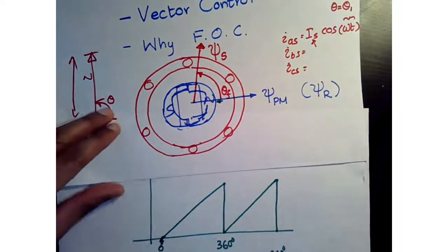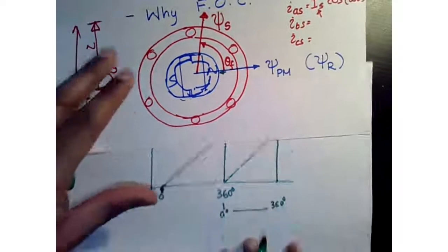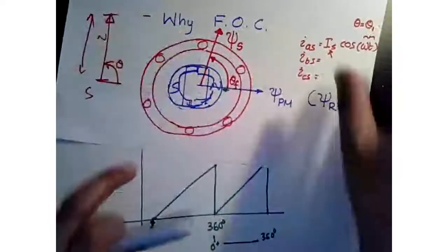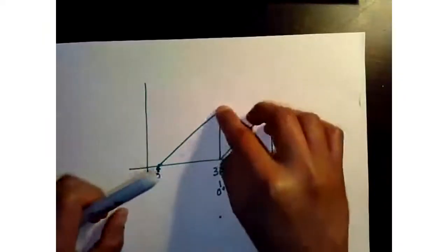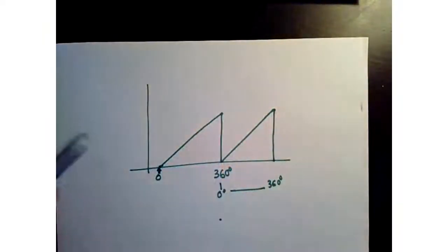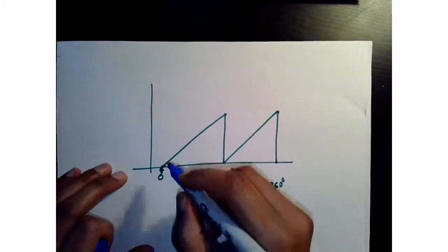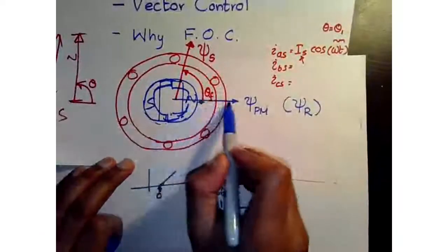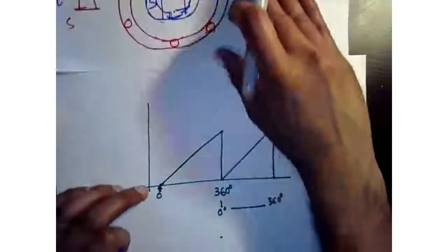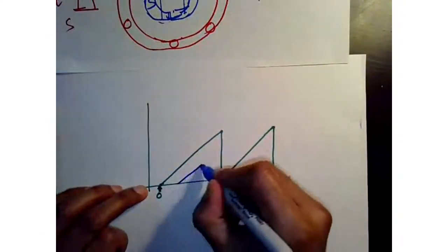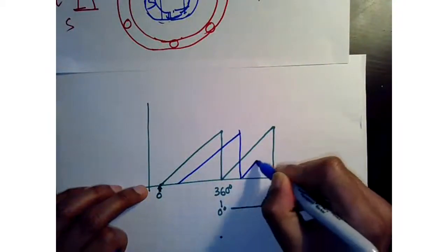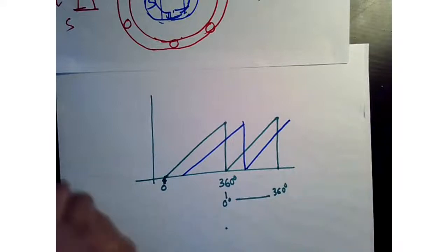Instead, what people do is mount the sensor on the motor, and when you look at the true flux alignment based on back EMF, you will see that there is a constant offset, because they are not properly aligned.